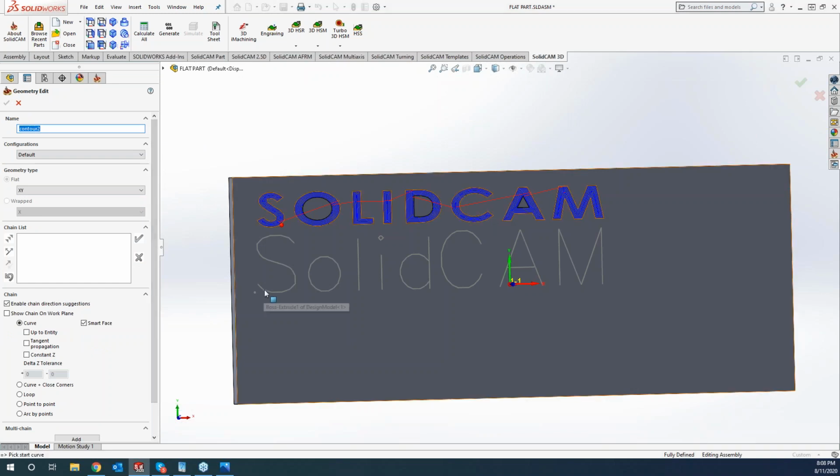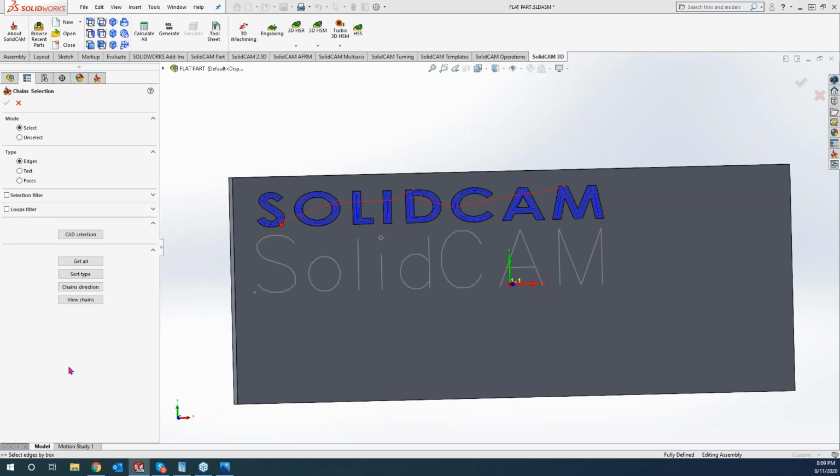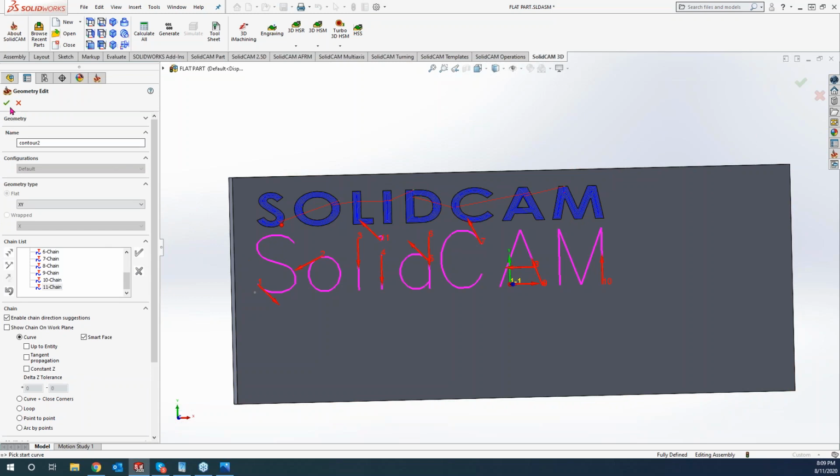Now, we can come in here and grab each individual line, but we'll let the software do the work on this one, and we can go down to the multi-chain. Now, with the multi-chain, it will actually pick up text. So a couple different ways of grabbing your text is come over here and select the text, and once your mouse cursor has the little text icon on there, so you can see I have a little A symbol next to it, that means I can click there and it's going to grab all that text file. So if I just click anywhere in there, you'll see it turns it yellow, and we can hit the green check mark, and we can see all our chains in there.